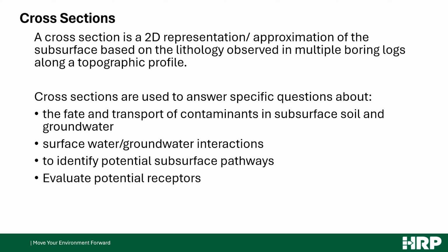You don't just want to go into a project and generate cross-sections needlessly, because they do take some time, and you should use them as a tool to answer specific questions that you need to know to further the site investigation. So specifically, the fate and transport of contaminants in the subsurface in both soil and groundwater are usually critical to the investigation.